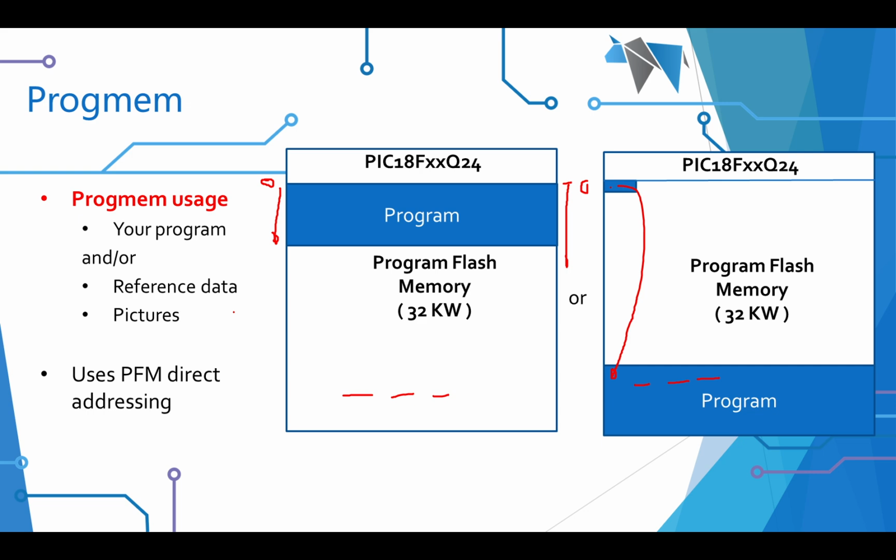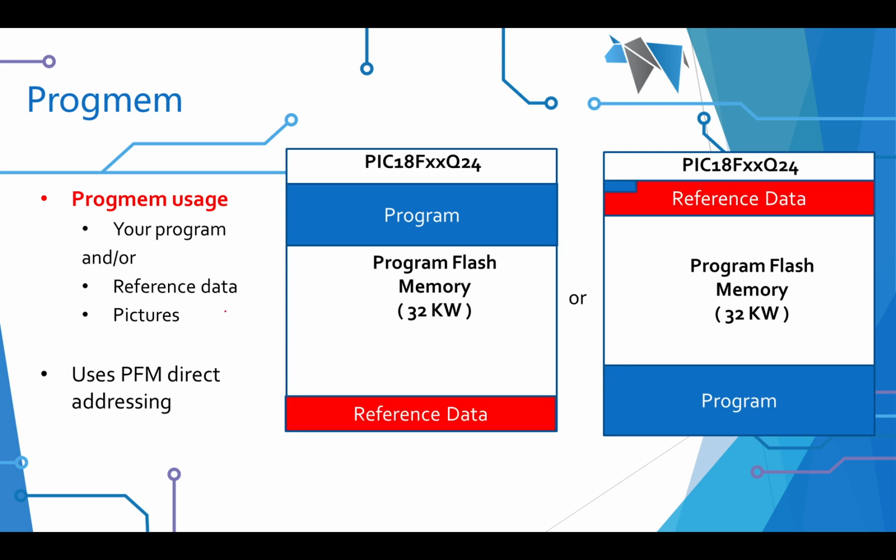And we're going to see an example of doing that. Now, that means that you could write reference data, lots of reference data, at the top of memory here. You can write it at the top of memory, or you can write it after your bootloader. Just be careful, not your bootloader, your jump vector into it. So that's the jump vector. You can put reference data anywhere. So you can do that, and I'll show you different techniques to make that work really quickly,